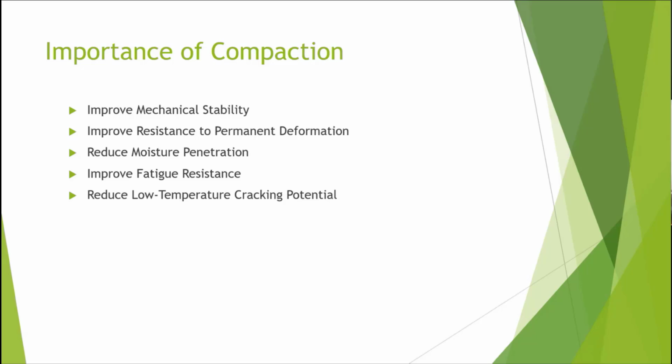Moisture, I don't care what kind of pavement it is, two-track, gravel, concrete, asphalt, moisture is the killer of pavements in our part of the world. And your first point of being able to address that is density or compaction during the paving process. And then the last one's important too, just like moisture penetration: cold air penetration into the mat.